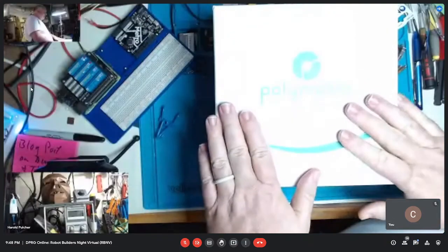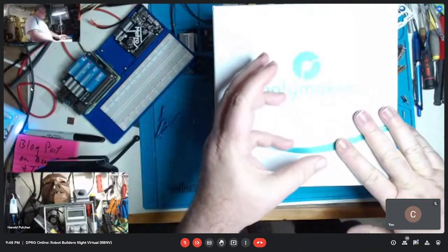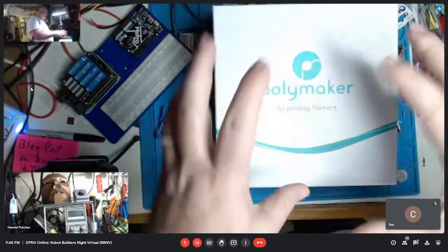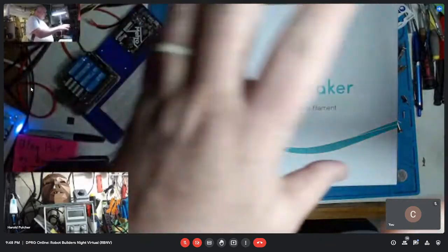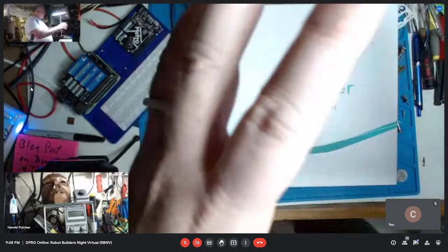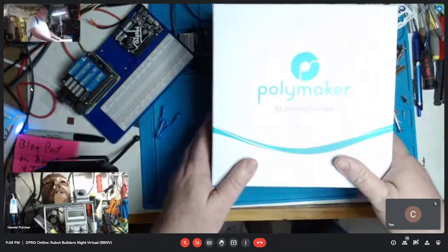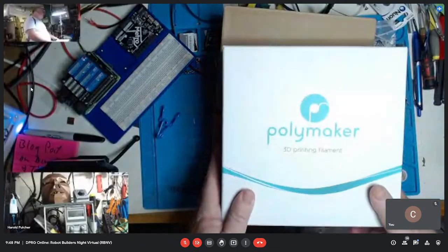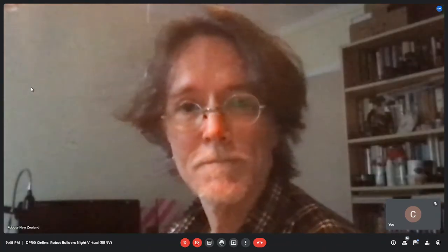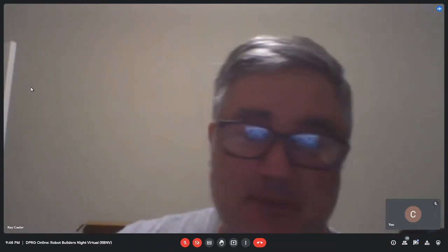Did you call it nebulized alcohol? Yeah, basically what you do, as I understand it, is you get one of those misters that people use, and you pour alcohol in it, you put this in an enclosed volume, and you nebulize it so it interacts with the outside of the PLA printed part, and it's supposed to smooth it all out. Nebulization is an actual word, I think. I've not heard the ization of it, but nebulizer. Cool. It sounds like something you put into a cocktail. Sounds pretty nebulous. Medical equipment used for respiratory therapy.